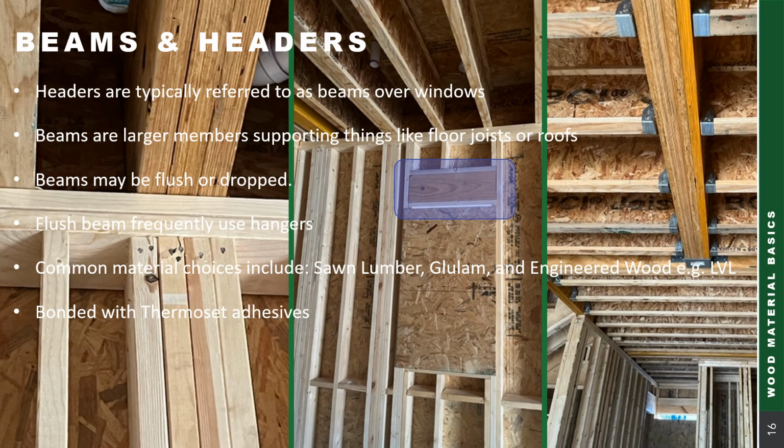As far as beams, they could be flush or they could be dropped. And so to give you a little bit of understanding on that, a flush beam means it's the same depth as the floor system. You could alternatively, if you don't mind having that beam visible, drop it down and have the I-joist run over the top of that if you wanted to.